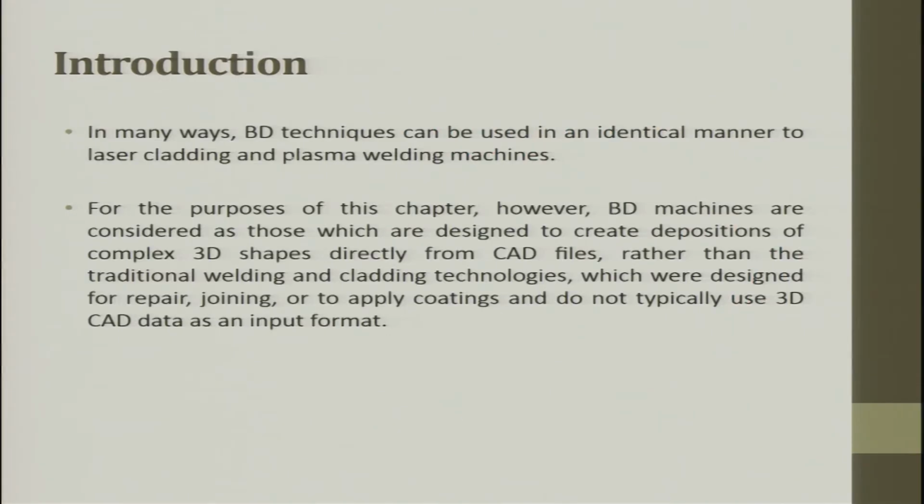In many ways, BD techniques can be used in an identical manner to laser cladding and plasma welding machines. For the purpose of this discussion or chapter, however, BD machines are considered as those which are designed to create depositions of complex 3D parts directly from CAD files, rather than traditional welding or cladding techniques, which were designed for repairing, joining or applying coatings and do not typically use 3D data as an input format.